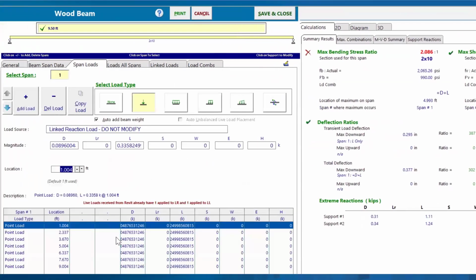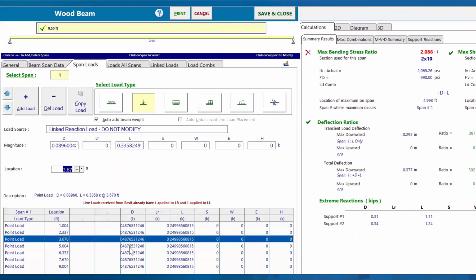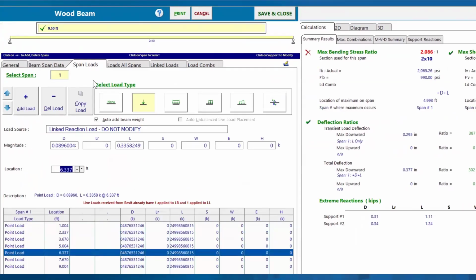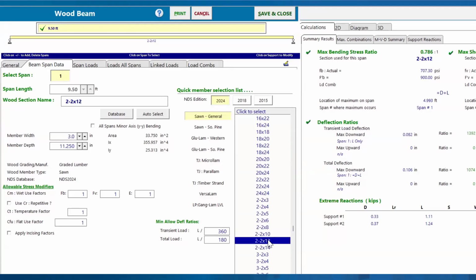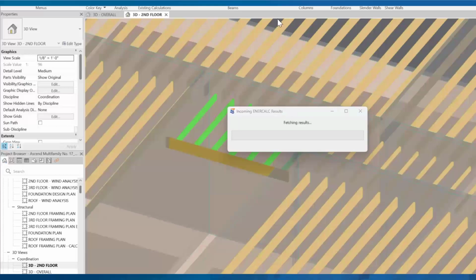So now that our header is fully loaded with each of those joist reactions from the corridor, we can do an accurate design, a final sizing that considers the true structural effects that this header feels. We didn't have to copy and paste. We didn't have to manually apply those loads, but we have the ability to get an accurate design on the fly.